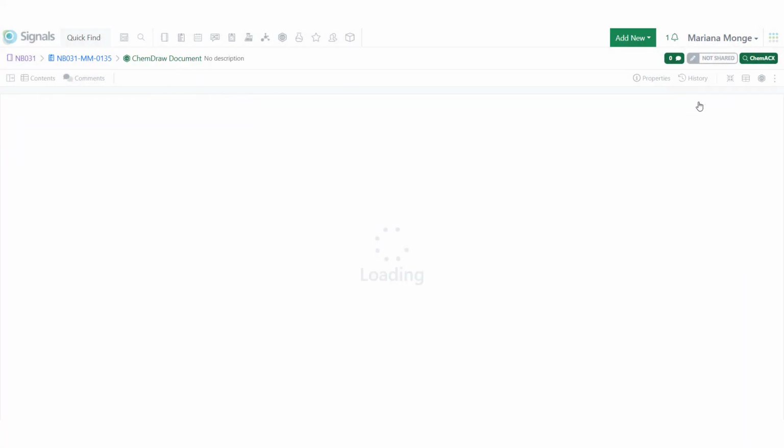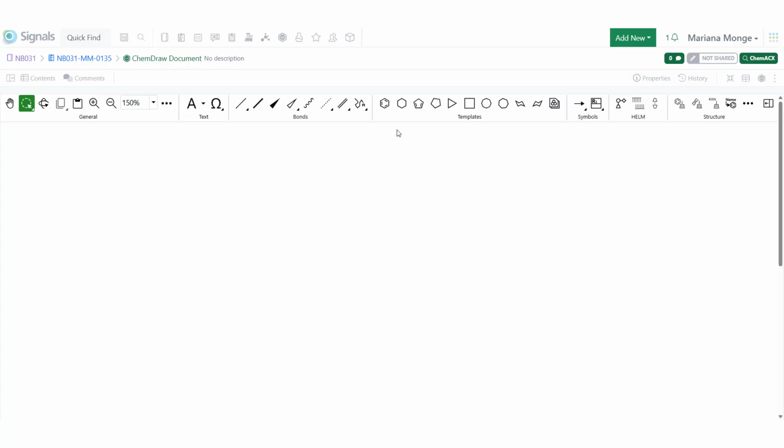Now, let's select one of the predefined structures and click once in the drawing canvas. You can also include additional bonds by selecting the Solid Bond tool and clicking on one of the benzene carbons to create a toluene. Then select the Text tool, click on the end of the previous bond, and type OH to create a phenol. Once you have a structure, you can use tools like lasso or marquee to select and move the drawings to the desired location.